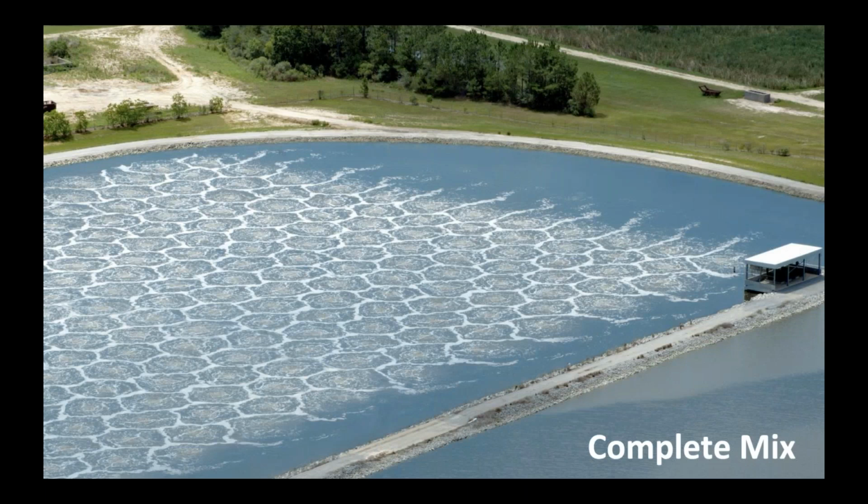And then finally, complete mix. This is a facility down in West Jackson County, Mississippi. It's a 7 MGD lagoon system that we upgraded. They created a complete mix zone on the back end of their primary lagoon, and this thing just rocks it. You can see the bubble patterns here. It is bubbles everywhere. It is completely mixed. All the solids are in suspension here. You get very, very fast treatment through this particular zone because of the mixing. And so that's when you get the best and highest treatment, with complete mix.